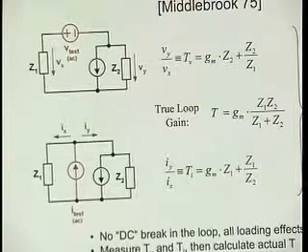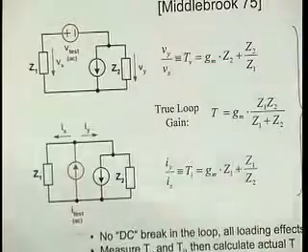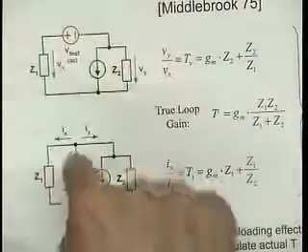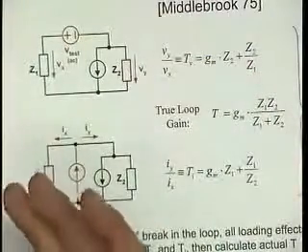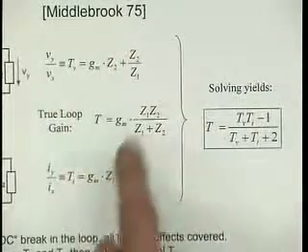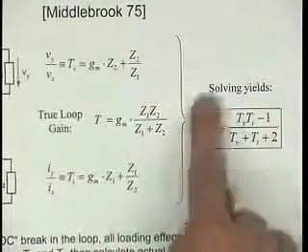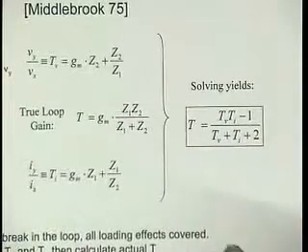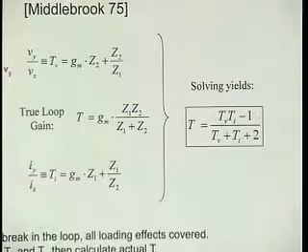The alter statement gives you an opportunity to go to a certain point in the SPICE deck, run certain analyses and so on. Then you change your circuit using these alter statements. Basically, you rip out this one, you stick in this one, in this case, and then you run another analysis. By doing so, you get all the right things, TV and TI, in one fell swoop, and then all you need to do in the post-process is type in this equation and do a Bode plot. You're done. It's not that terrible.